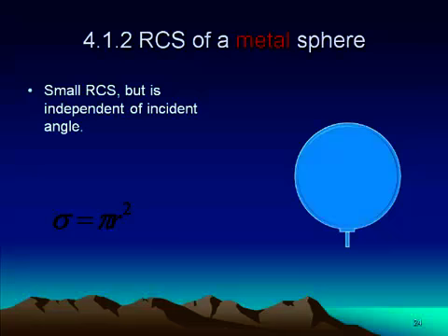With this, you can get an idea that the more the RCS, the more the reflected signal is going to be, and hence at the receiver you will have very little doubt about the presence of the target, and accordingly you can also make an accurate calculation of the range.